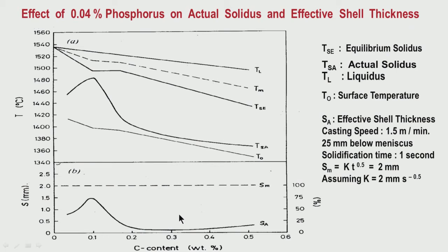This has a lot of implication on the strength of the solidifying strand, because the strand consists of what? Strand consists of solid shell, mushy zone and liquid.